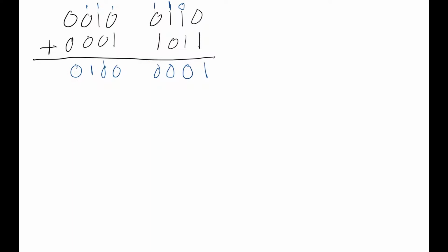Now, instead of building a circuit that takes in these 8 characters, in our computer they're actually going to be 16-bit numbers, so really twice as many numbers as you see here. Instead of taking in all of the numbers at once and adding them all together, we'll make a circuit that focuses on a smaller problem of just adding these two bits together. So we'll get one input from one of the numbers and another input from the other number that we want to add. We'll also grab another input for the carry in. And this is the carry in from the previous bit.